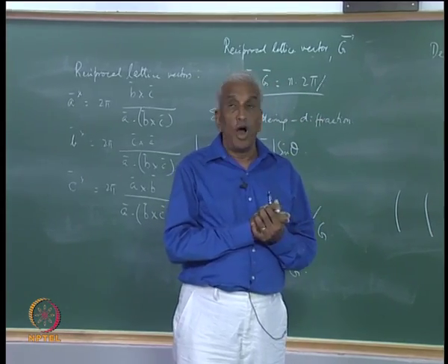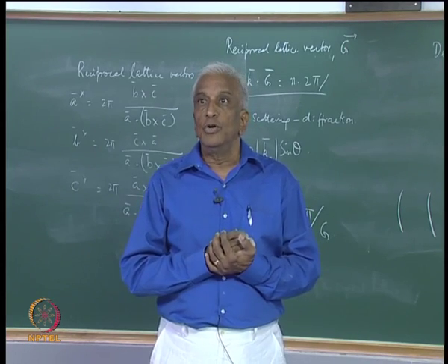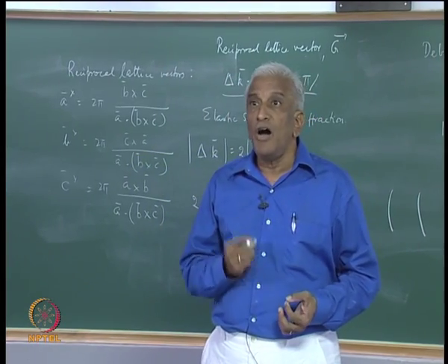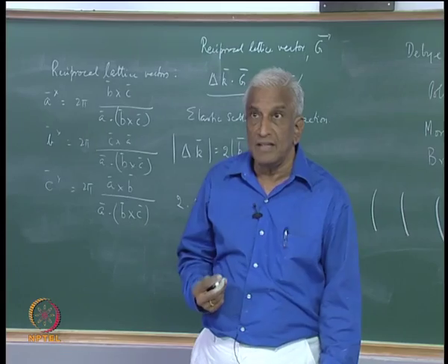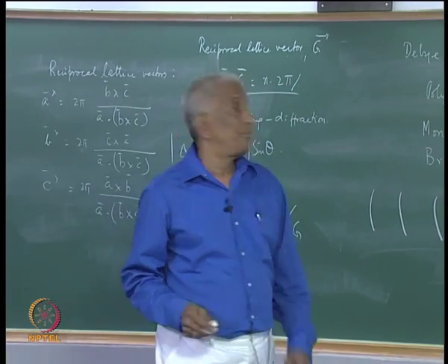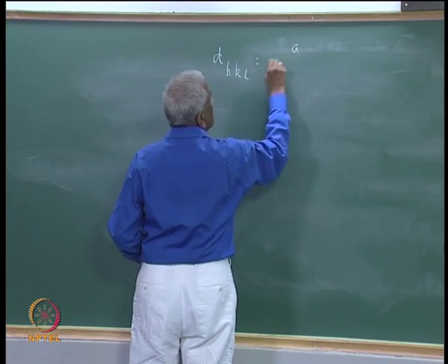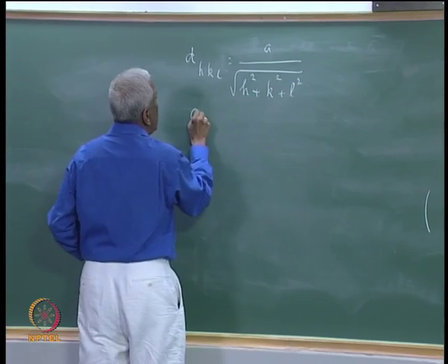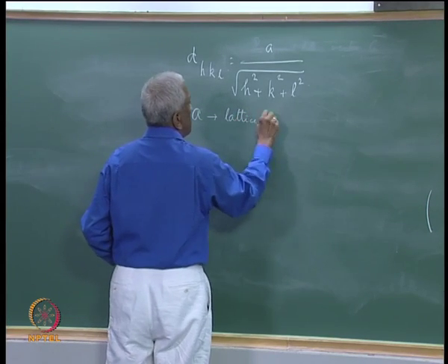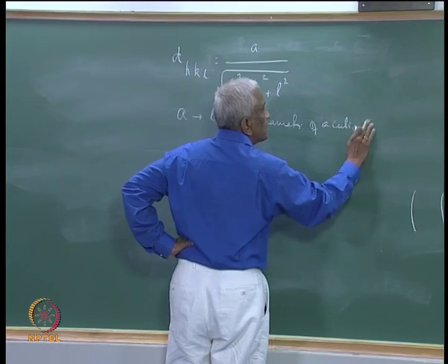varying intensities. So, how to interpret the X-ray pattern? It is easier for simple cubic structures. Such a simple description of how the crystal structure can be determined using the diffraction pattern generated by a simple monatomic cubic lattice is shown in this figure, and is described now. So, if you have a cubic crystal, then the condition is, we already mentioned this in an earlier lecture, where a is the lattice parameter of a cubic solid crystal.